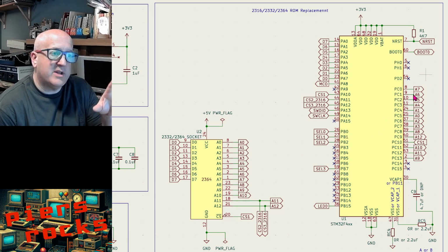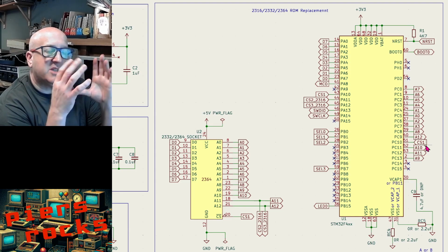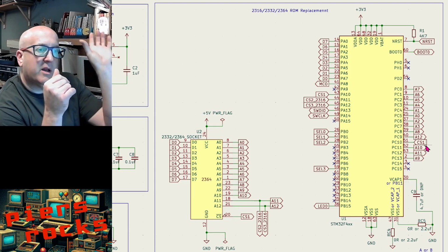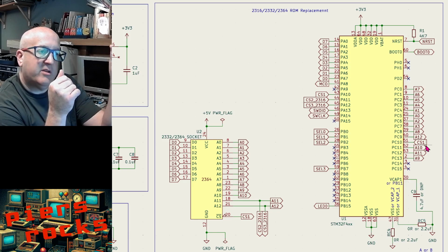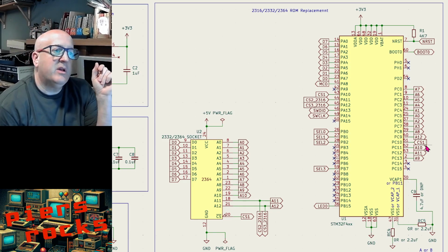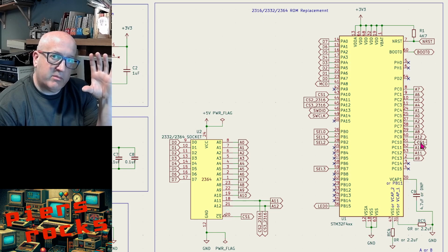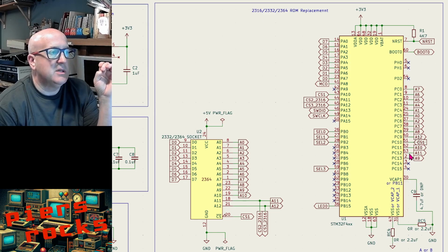You can see I've got all the address lines and the chip select line on the same port, and I've got them on pins 0 to 13. That means I can take the value that I read and I can use it as an offset into RAM, and it only needs to be a 16K address space. 16K rather than 8K because the chip select line is embedded within that group of address pins. We'll come on to why that is in a moment.